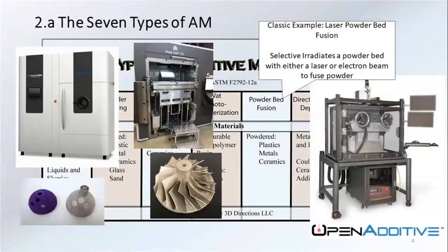Electron beam typically has a rougher surface on the hull than laser powder bed fusion. A lot of people are using electron beam for the same lattice structures that you're doing with laser powder bed fusion, but if you need that surface finish, you typically need to go with the laser powder bed fusion side. They both have their quirks, they both have their uses. Depending on what type of manufacturing you're doing, you might want to go with the electron beam route, to delve through the nuance of the differences beyond what we're going to go through today. But certainly if you have questions about that, you can reach out to me after the meeting. My information will be on the last slide.